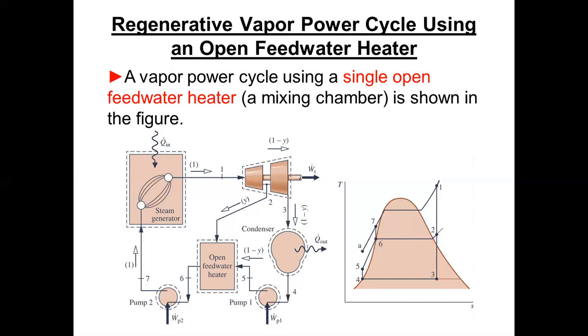So that's the fraction, or it's 80% of the steam flow that can generate power from state 2 to state 3. And so the power generation is what goes on with the full steam flow from 1 to 2, plus the power generation from 2 to 3 that only has 80% of the steam flow to push it.